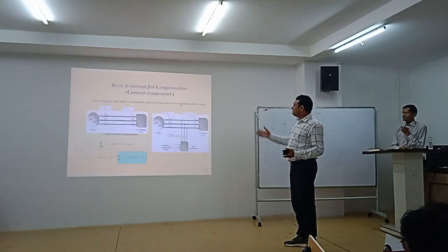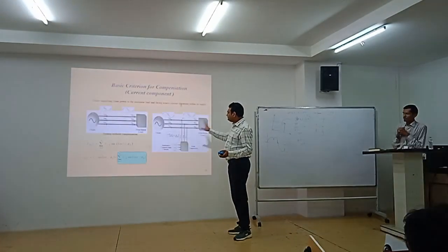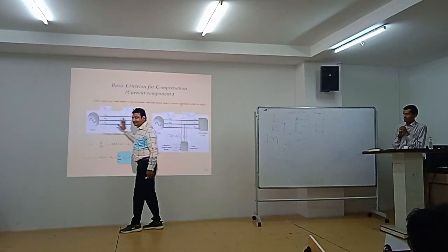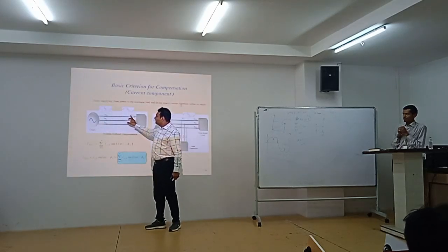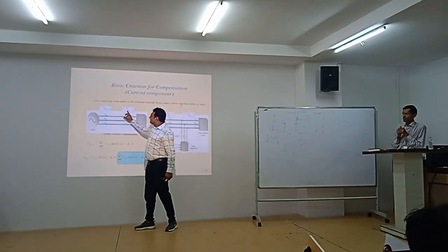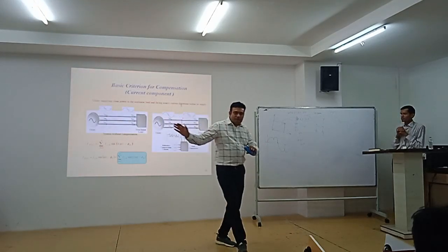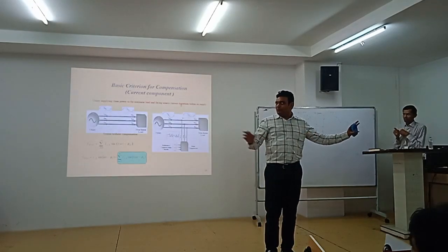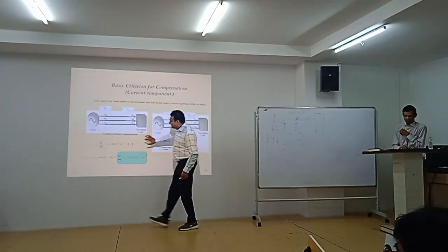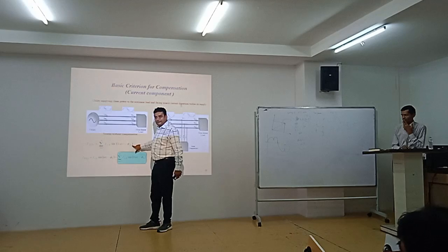Limitation with frequency domain method, this is very important. If it is like this, this is your system: utility, non-linear load, load current, source current. As it is a non-linear load, it appears on the source side also, right? But the current will reduce a bit. Why? Because its travel is long. So the current spectra, if you take load current or source current, is this, right?